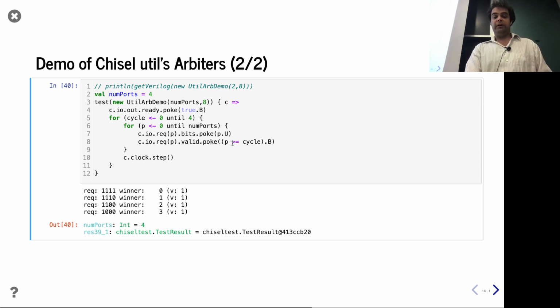And we could do various things, right? Here I have it, greater than or equal to. We can make this equal, and you can see whichever one requests by itself could win. We could imagine other scenarios, right? What if, for example, we say P is less than 4, which it will always be. Well, guess what? That port always wins, right? Because it's the same request coming in, and we have a fixed priority, and so it's going to keep winning.